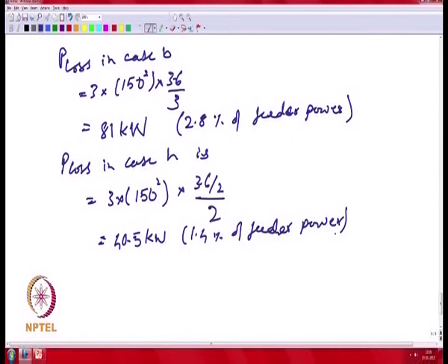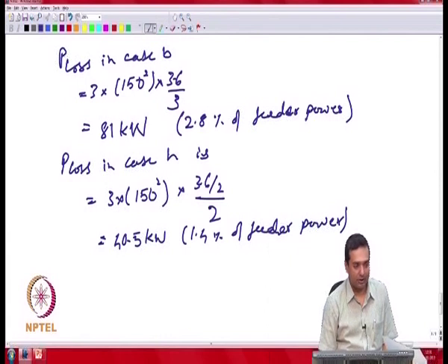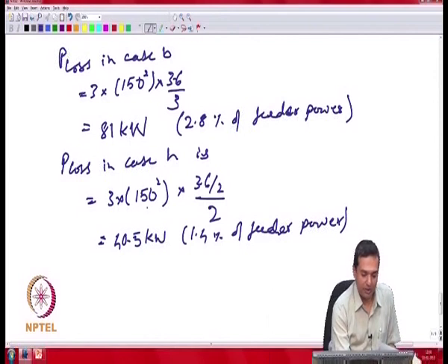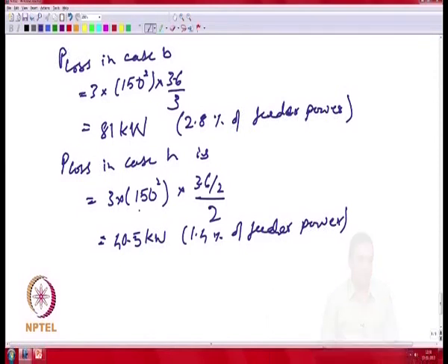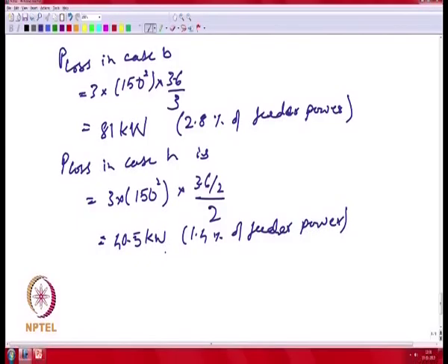And often the reason for putting parallel conductors is not from the power loss reduction perspective, it might be to increase the capacity of the line. So, the number that would be used when you have parallel conductors would not be at the same level of loading, there would be increased loading, because your purpose for adding the parallel conductor is to actually serve more loads, often. And the limitations of how much power dissipation is often related to what is the temperature rise that the conductors could see, which would also limit how much loading can happen on a per kilometer basis.